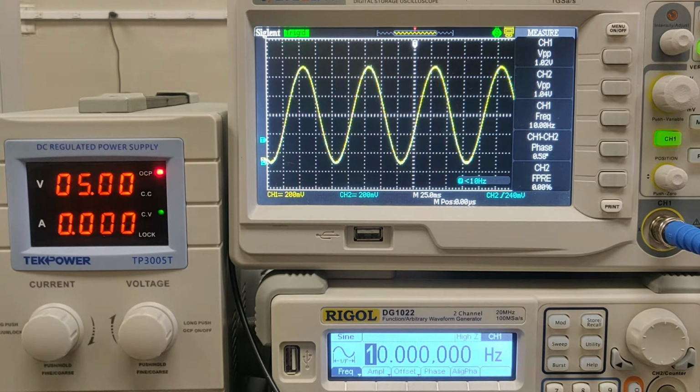And we're going to be finding that high frequency cutoff for these different op-amp circuits. So let's start by finding this high frequency cutoff at this 5 volts DC, which is also our -3 decibel point. We haven't really used decibels since our RC circuit lab, but taking 20 times the log of our gain, so 20 times log of 1 over root 2, will give us something that's roughly -3 on that scale.